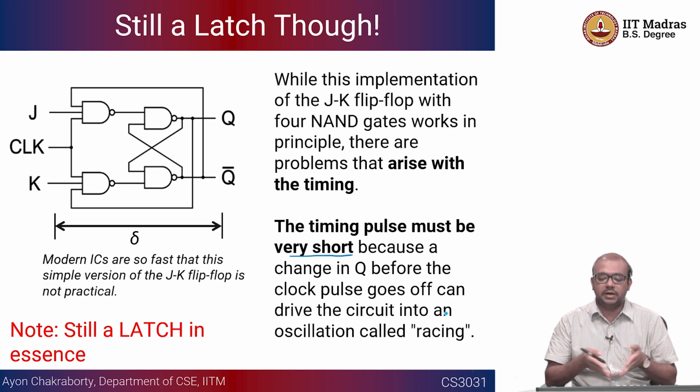So the only solution here, without making any changes to this circuit, is to make the clock pulse as narrow as possible. Okay, but in a real life situation, considering all sorts of manufacturing defects and so on, it is very difficult to make a clock pulse very, very narrow, comparable to the latency of the NAND gates, right.